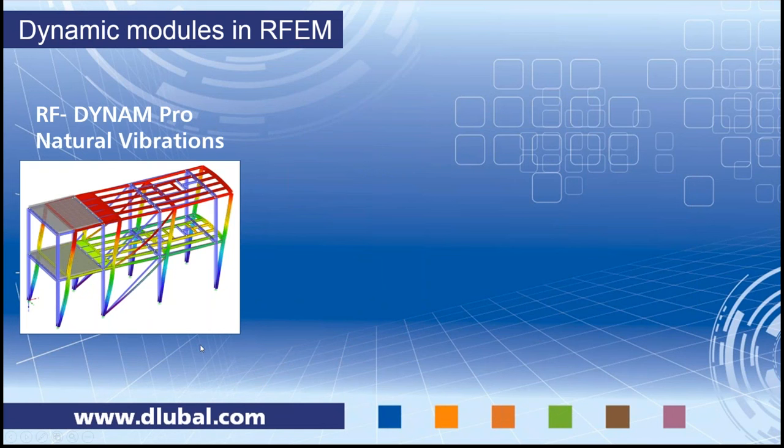This is what you always need, and it performs an analysis of frequency and mode shapes for members, surfaces and solid models. You can directly import masses from load cases. You can build combination of masses in so-called mass combinations, and you can import stiffness modifications, axial forces, failing or deactivated members, or stiffnesses from RF-CONCRETE as initial conditions. So these are just a few examples. We have 4 eigenvalue solvers available, which I explain more in detail when we go through the example.